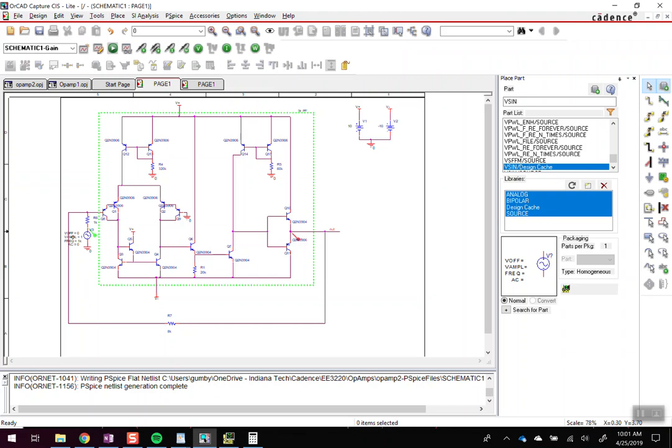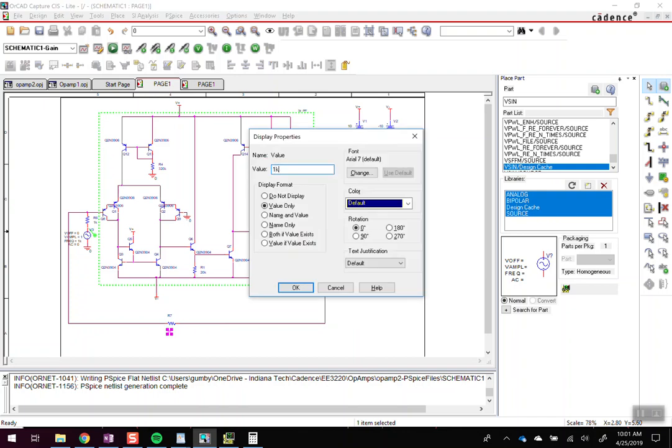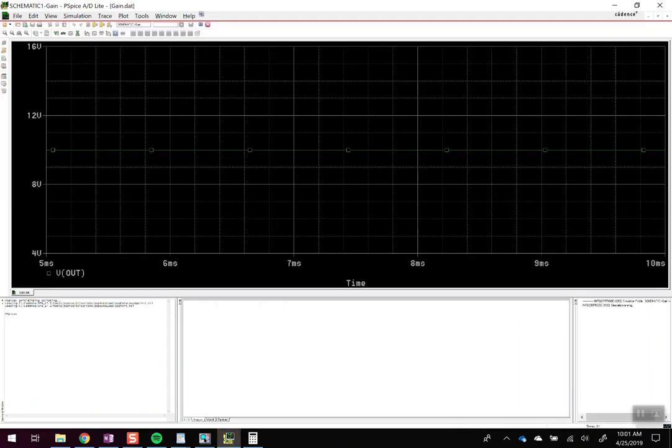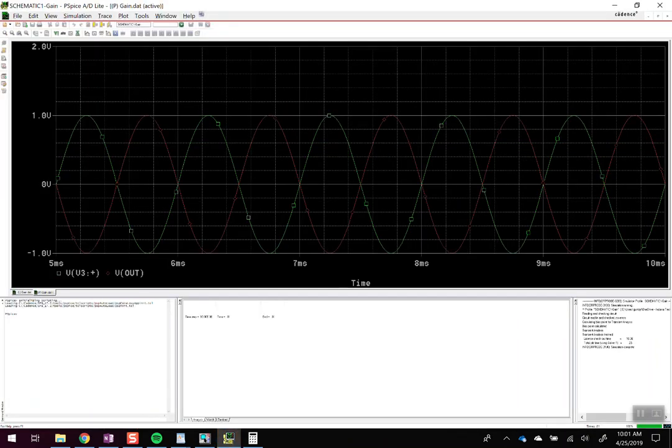What we want to do is figure out maybe what the gain bandwidth product would be. Well, what we're going to do actually is set the gain for 1. Now this isn't going to be an exact way to measure it, but it's going to be roughly okay. So we can see they're just out of phase, right?